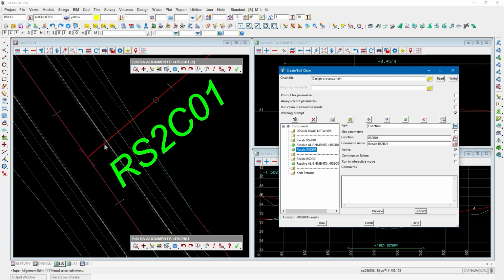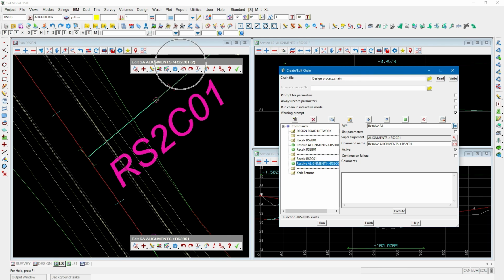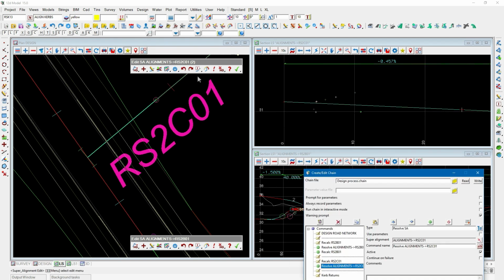Again, it's definitely not at 90 degrees anymore. So when I recalculate the side road, or CO1, that would then automatically get recalculated and produce the new vertical geometry off these 2 points. And you can see it's not 3% because of the skew angles. It's 2.6 essentially, or negative 2.6 there.